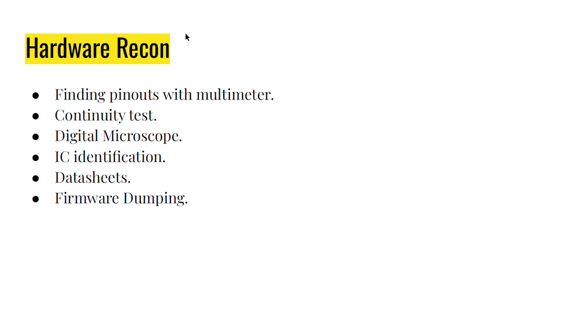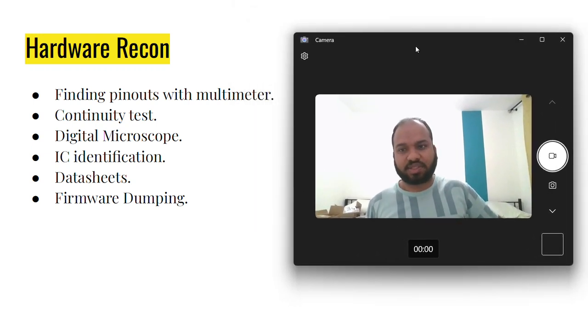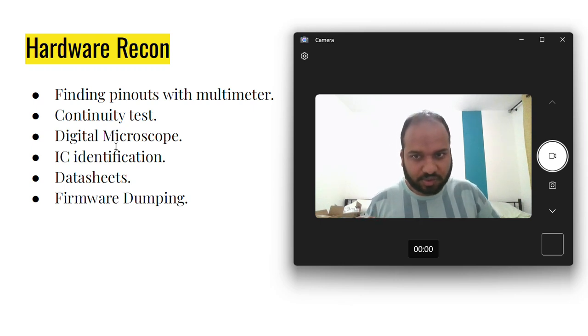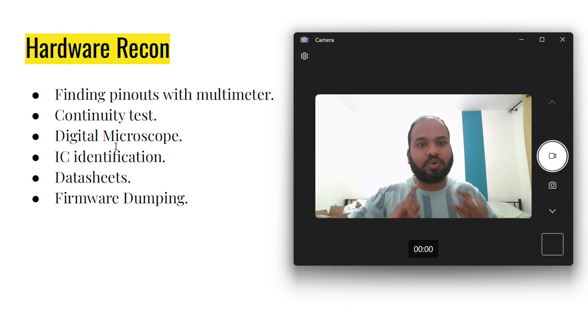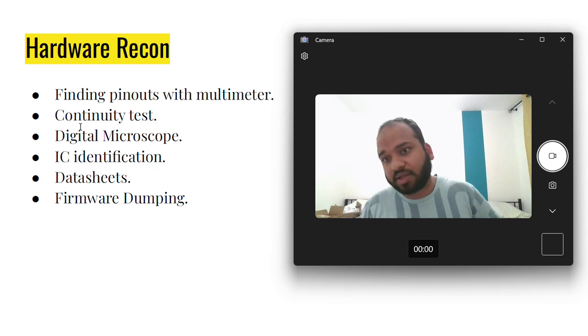So now, hardware recon. How would you do a hardware recon, guys? Let me make you guys think. Before even coming to this slide, you can just get back, take that set of knowledge, and use it to do hardware recon level things. What I'm actually trying to say is hardware recon can be done by finding pinouts with a multimeter. Just do a continuity test. Just use a digital microscope in order to understand what kind of protocols are there.